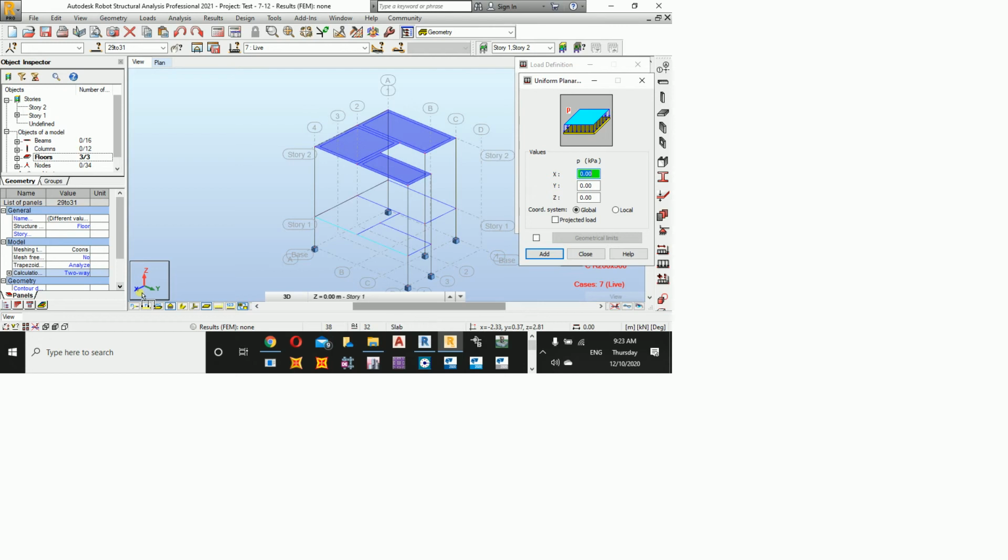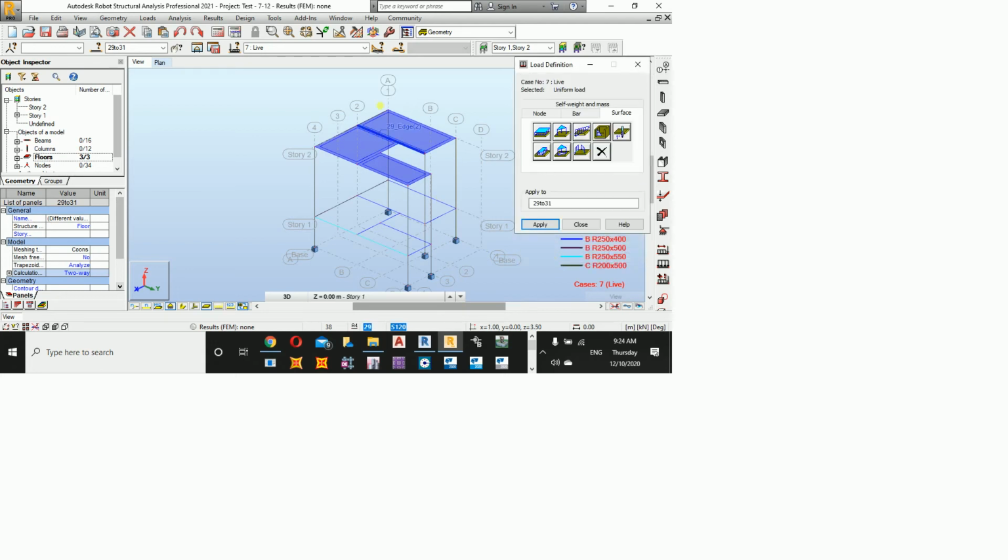Now, one thing before you put your loading in Z: your Z positive goes where? Up or down? According to the coordinates, it goes up. Your loading is going up or down? Down. So it should be minus, for example, let's say minus 2. Are we clear? By default, these have been already selected, we pre-selected them from the beginning. So I'll just click apply.